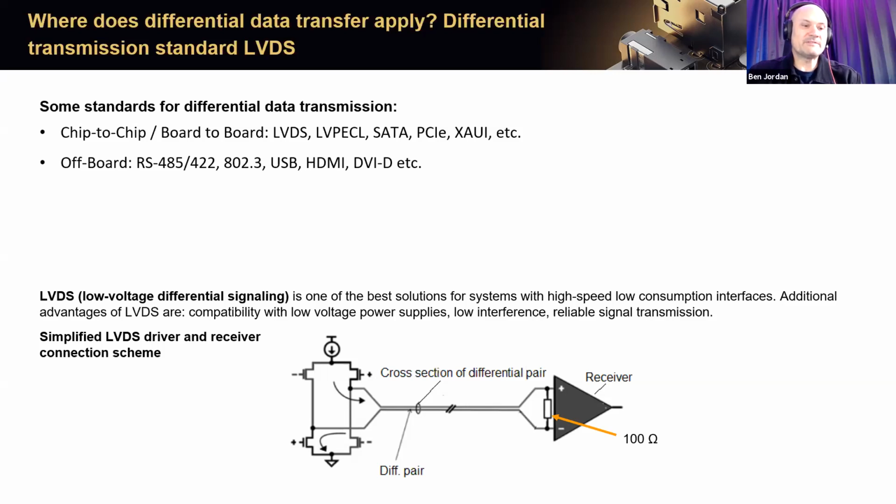To get proper signal integrity and to not have excessive ringing or reflections on our diff pair, differential signaling standards are invariably defined to have a differential termination or load that's resistive, and typically that's a parallel termination from the true signal to the complement at the end of the line close to the device, but not necessarily, but usually that's where you place the termination resistor, towards the receiver end of the line.